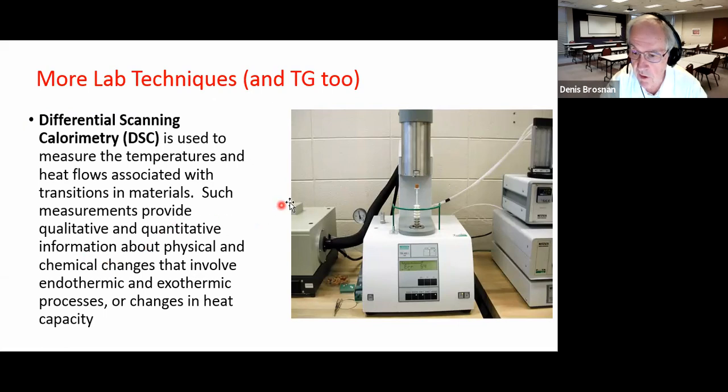But nevertheless, a specimen is suspended on a specimen platform here. The furnace is brought down over the top of the specimen. And so we can measure thermogravimetric analysis on heating. TG, gravimetric analysis, that's the weight change on heating. We also can measure energy flow by comparing what's happening within the specimen to specimens of inert material.